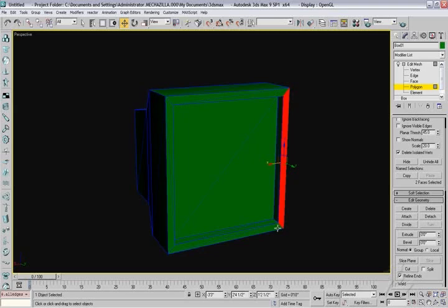Now if I were going to be putting a texture map on here, I would want it to have all four of these as one and just paste it on there. That way you get kind of an alpha channel showing up, or a transparency showing up right through the center. So I could use a photograph on here, or some custom texture such as a plastic or whatever have you. So what we need to do to get rid of that is concentrate on these visible edges in here. And the way we do that is go over into the modifier list and click on edge mode.